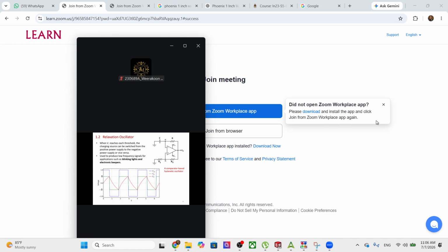Why 100 times higher or more? If I say 1,000 times, that means I am restricting too much, that means 0.1 percent. Anyway, we have to tolerate the capacitor and resistor tolerance of at least 5% or 1%, isn't it? In general, resistance can be 10%. But if you go for SMD components, probably you can go for 1%.